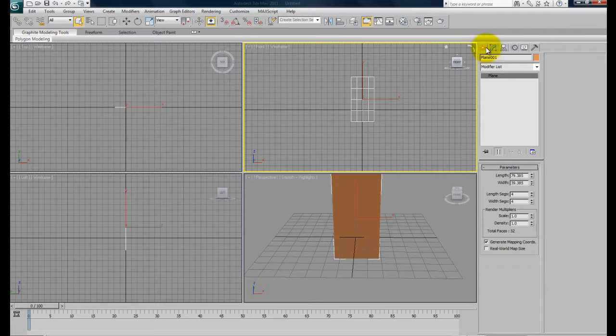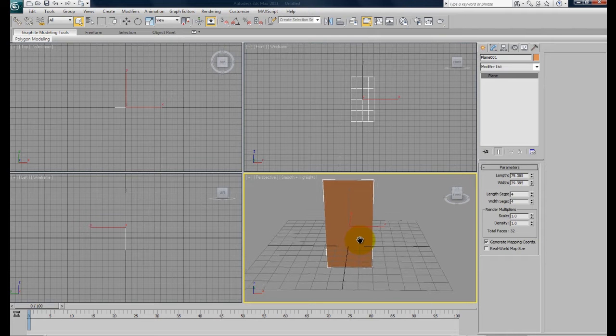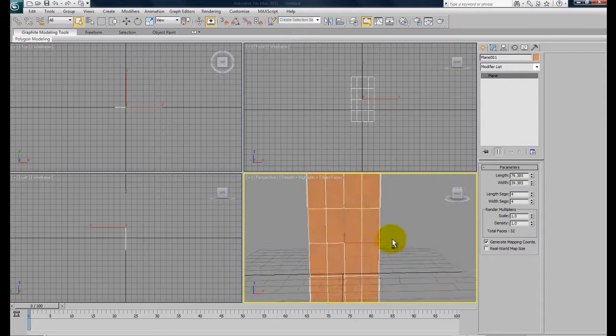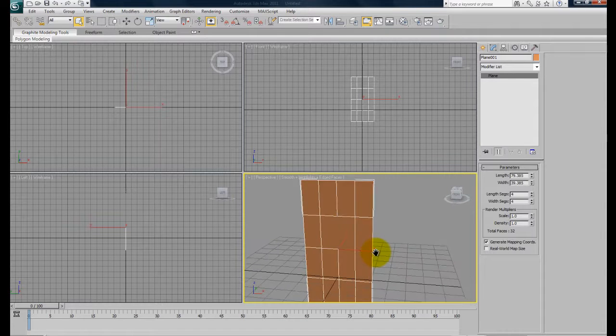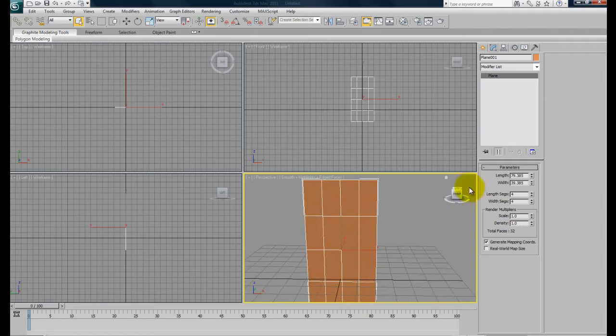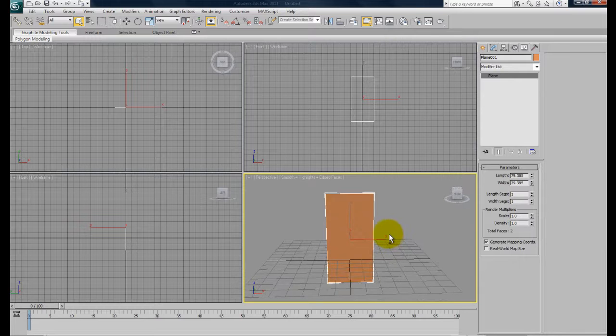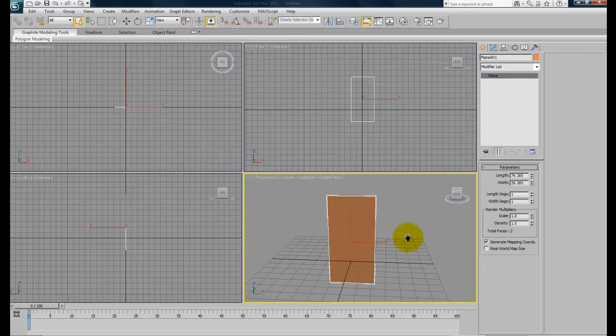Then go to your modify setup over here, and on the perspective view, turn on F4. Then you can see your wireframe on your polygon object, and down at the setting here, reduce it to 1. We don't want so many polygons, just one sided polygons.